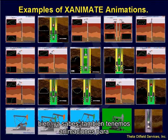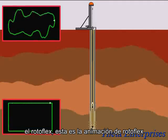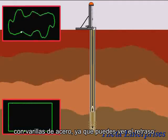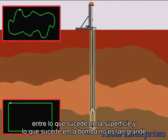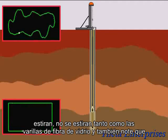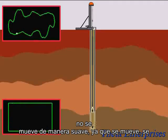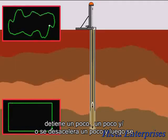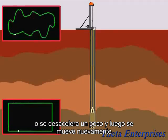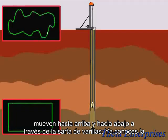We also have animations for different kinds of pumping units, like the Rotaflex. This is a Rotaflex animation with steel rods. As you can see, the delay between what happens at the surface and what happens at the pump is not as big, because even though the steel rods stretch, they don't stretch as much as fiberglass rods. Also notice the movement of the plunger. It's not moving in a smooth manner. It moves, pauses or slows down a little bit, then moves again. That has to do with the waves moving up and down through the rod string.